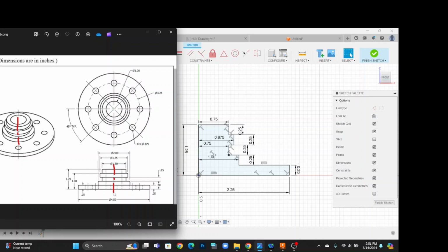While creating the sketch, I have drawn the geometry to the right half of the axis of symmetry. Since I'm drawing only the right half, all of the horizontal measurements which are along the x-axis are cut in half. For example, the diameter of the base of the object right here is shown to be 4.5 inches.